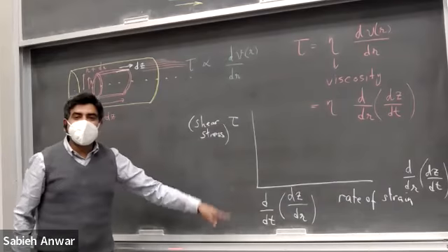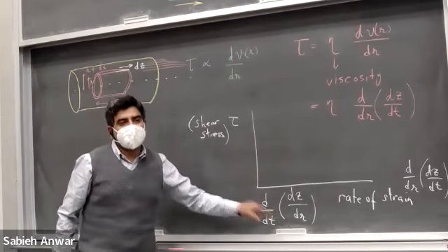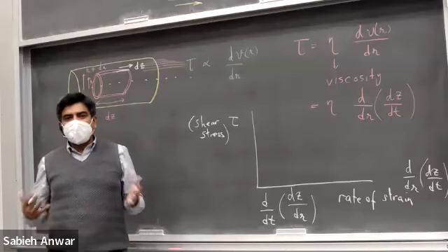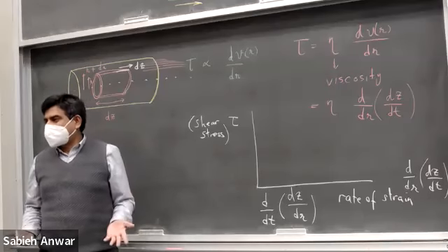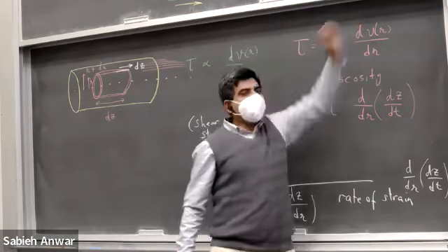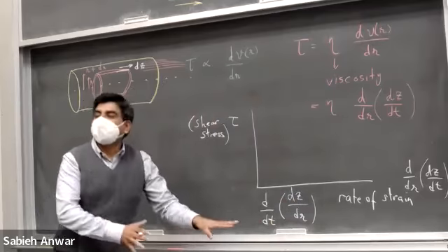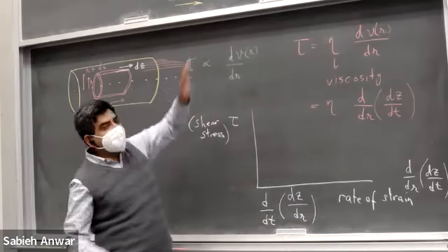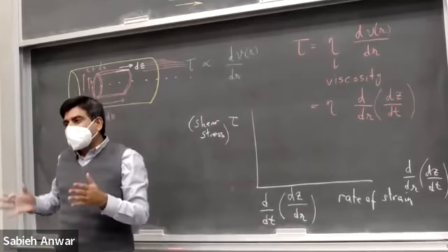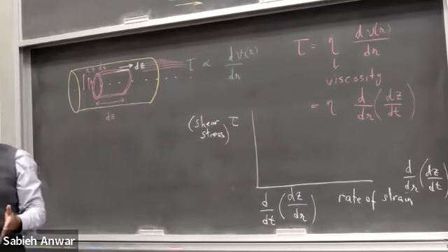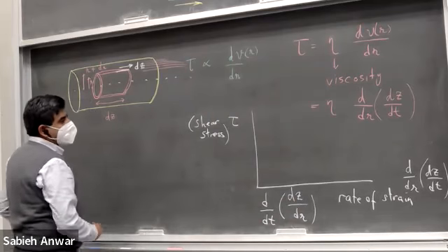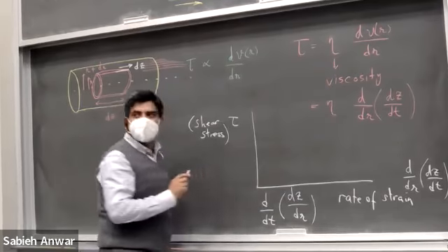So this is indeed a rate of change of strain, right? So we're trying to look at Hooke's law for fluids. What we've done is replace the strain in a solid with the rate of change of strain, and replace the compressive or tensile stress with the shear stress, because it's the shear stress that is making the object move here.